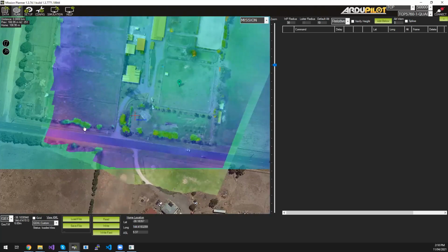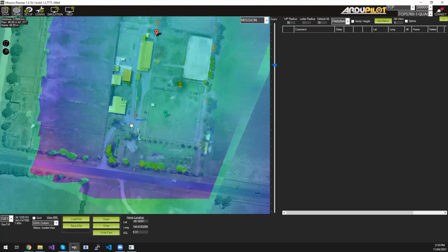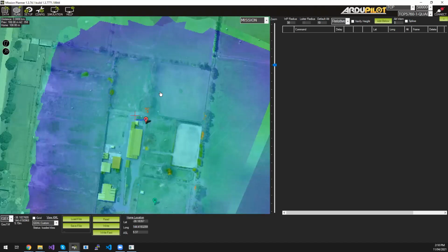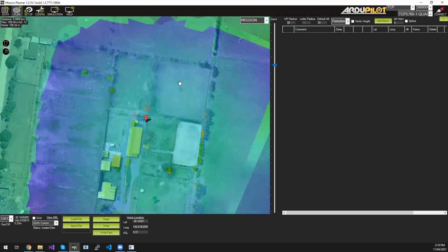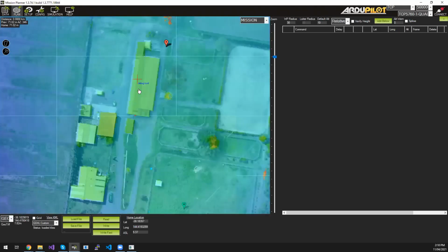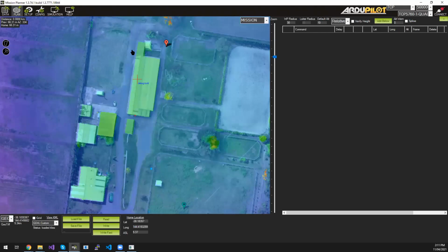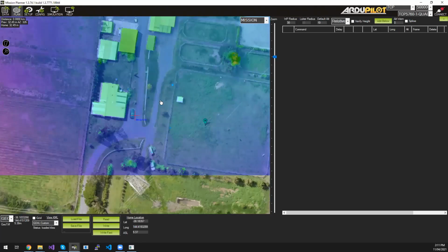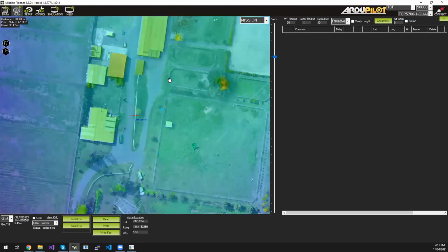and it'll render an overlay showing the elevation model. At the front of the property here, you can see trees. The top of the tree here is 7 meters, and then if I mouse up a bit, 2.6 meters. So you can show the trees, you can show the buildings. The trees down the back of the property didn't work properly by the look of this, but I've just blamed that on the poor quality capture of the data in the first place. But buildings, you can see basically the edge of buildings. The roof of this building is 7.8 meters. The ground next to it is 5.3 meters. So you get high resolution data into Mission Planner, and then the knock-on effect of getting this into the copter to do terrain following or other things.